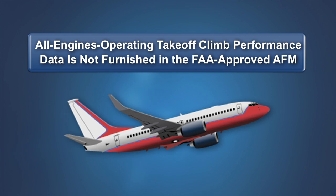As we have seen, there is a requirement to furnish one-engine-inoperative climb performance data in the AFM, but using this data to show compliance with a climb requirement published on the IFR departure procedure is not required by any operating regulation. Some manufacturers may provide supplementary all-engine climb performance data, but if that data is not available, pilots should use their knowledge of the airplane's normal performance capabilities to determine whether they can comply with this climb gradient on a particular takeoff.